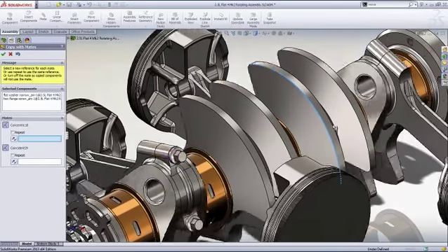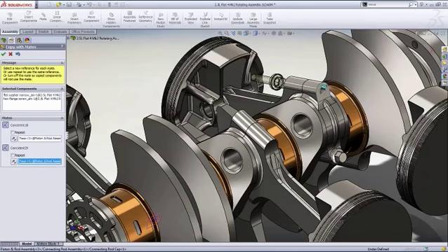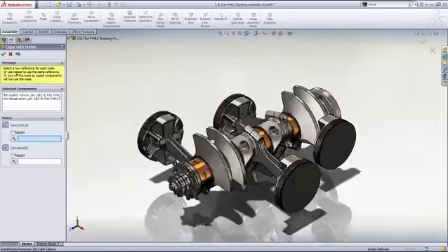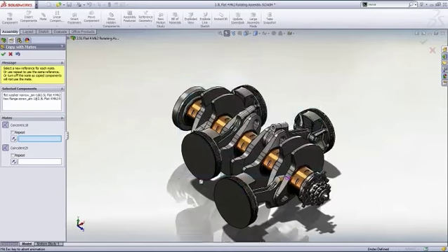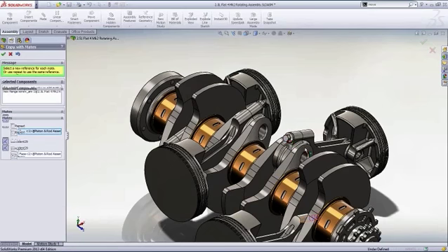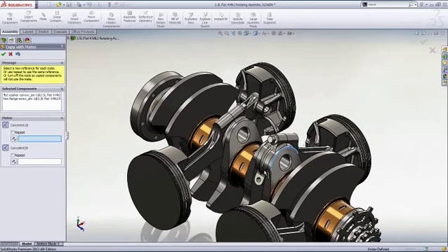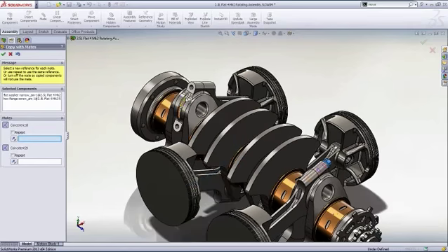It's really convenient when I have to do this over and over, and I can even move the assembly through its range of motion while doing this. It makes this whole process considerably easier than adding each one of these components one at a time. Though probably the longest tip I've shown, you can see that the process is pretty simple. Select the hole, then select the face. Right-click and repeat. Before we know it, I've placed 14 components with little effort.